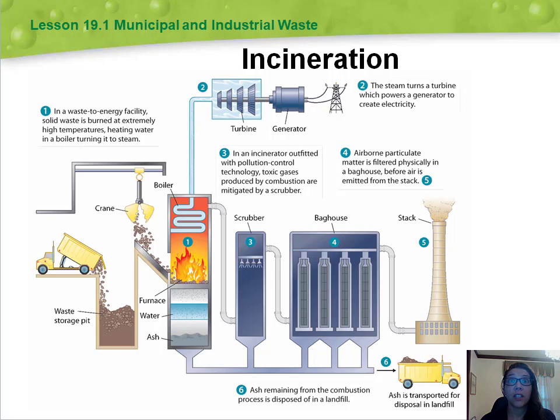At incineration facilities, waste is generally sorted and metals are removed. Metal-free waste gets chopped into small pieces so that it burns more easily. Incinerating waste reduces its weight by up to 75%, and it reduces its volume by up to 90%. As a result of real and perceived health threats from incinerator emissions and of community opposition to these plants, engineers have developed several technologies to mitigate emissions.